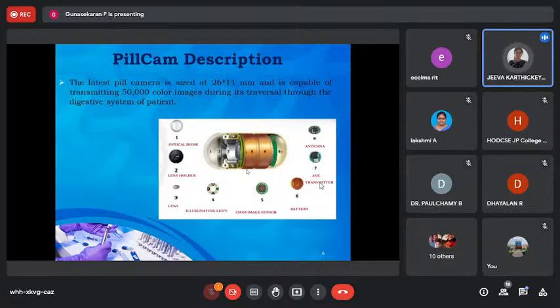First one, the optical dome. It is the light receiving window. The second one is the lens holder, which is behind the receiving window. Then the lens, the integral component of the capsule, is used for receiving the images in the GI tract. And here we use 4 LEDs. Then the CMOS image sensor is used to highlight the images and enhance the image quality. It also takes images at a 140-degree view, and it can detect images as small as possible.